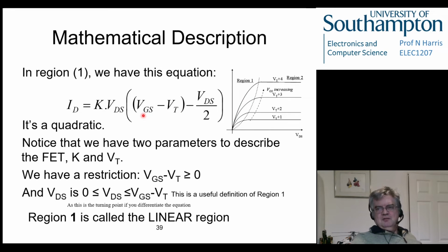And it's defined by VGS, which is the controlling voltage, the gate voltage, minus VT, so how far it is above the threshold, which is the cutoff voltage. So this is how far on it's on, minus VDS over 2. Okay, so we don't need to particularly worry where this equation's come from. It's a very complicated thing to develop. There's a lot more to it. There's a whole lot of other terms that are on the end of it, but this is the fundamental term of it.